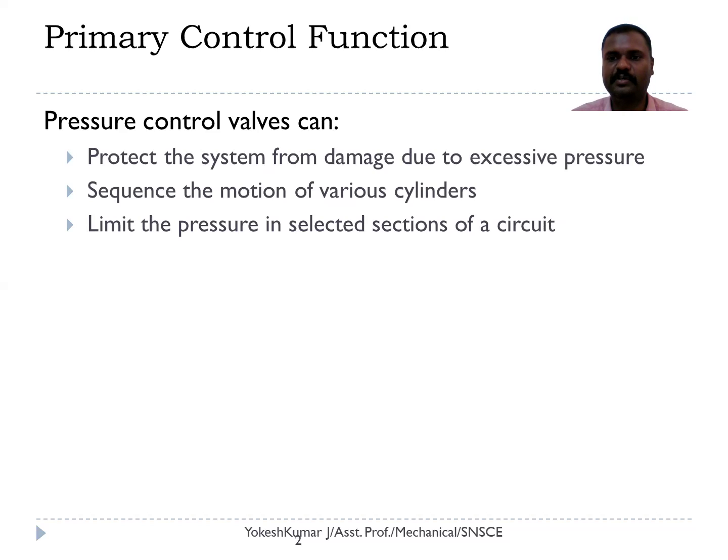If the pressure of the fluid exceeds the safety limit of the pipeline or any hydraulic circuit, it tends to burst, which will cause an accident and may take several lives. To avoid this, we need to protect the system against damage due to excessive pressure. For that, the pressure control valves can be used.